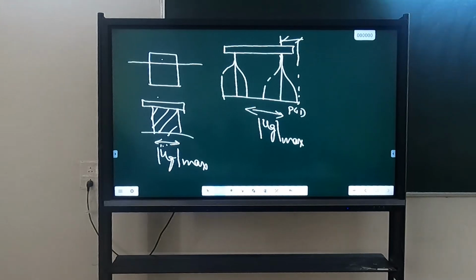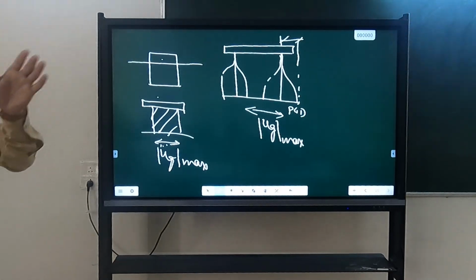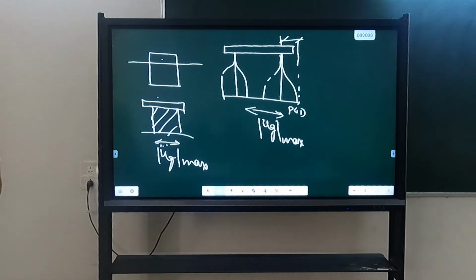Okay. So wherever an interface is there, wherever there is a change in the medium, there will be reflection and refraction. This reflection and refraction is also responsible for attenuation. Yesterday I talked about damping. So damping is just one way of dissipating energy. Another is this reflection and refraction. So part of the wave's energy gets reflected back and part of it gets transmitted. This happens at every interface, whether that interface is within the rock, rock versus soil, or different layers of soil.